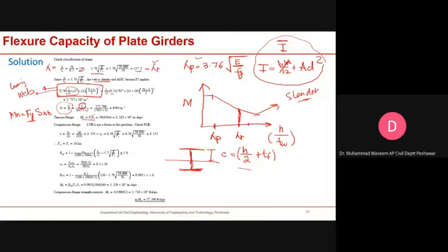So you can come up with this S value, which is the elastic section modulus. For example, this is the tension side and this is the compression side. On the tension side, this is the section modulus of your section. Once you know that, you can use the first limit state, tension flange yielding, and you just have to multiply it with the yield stress of the material.